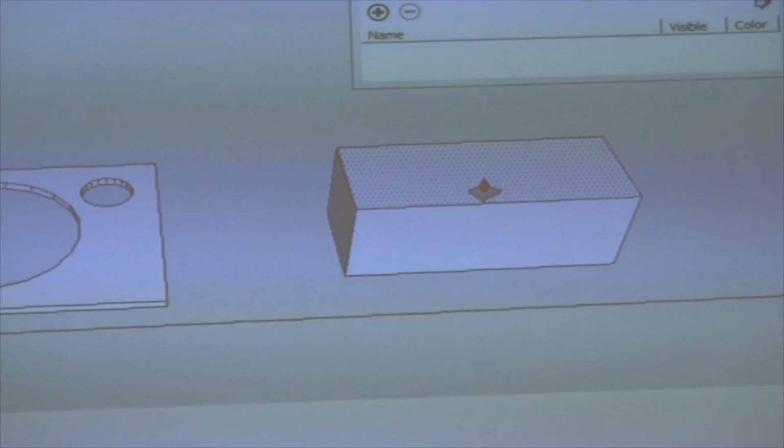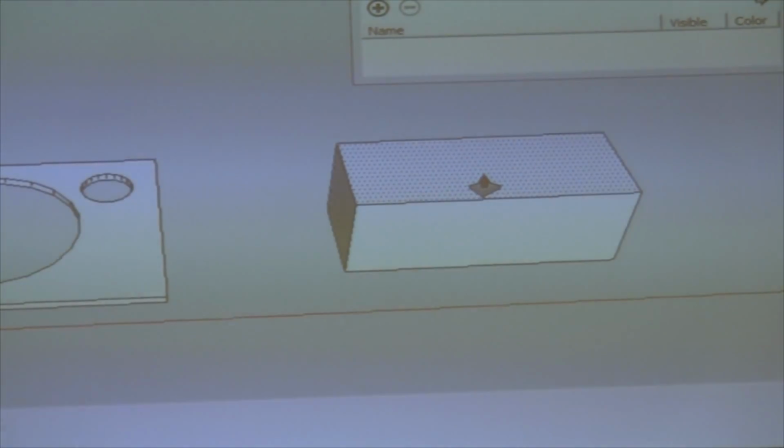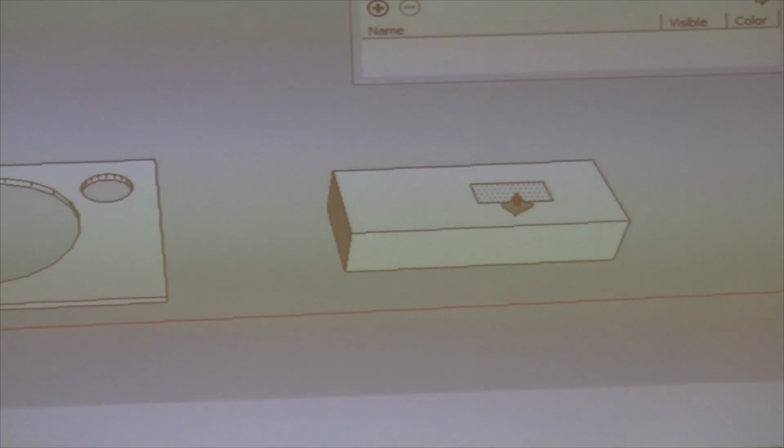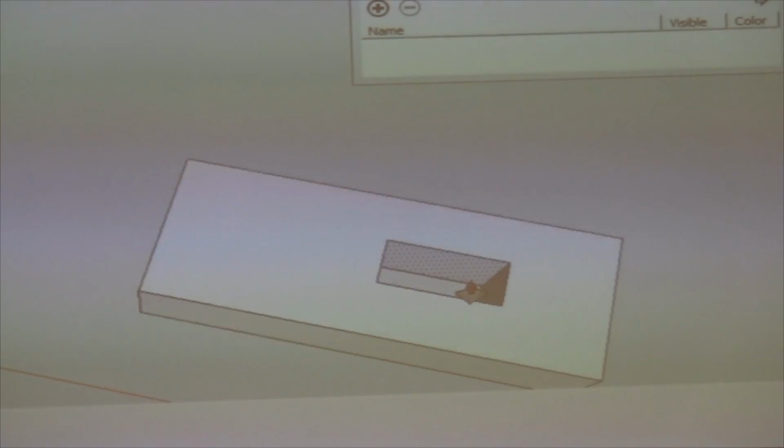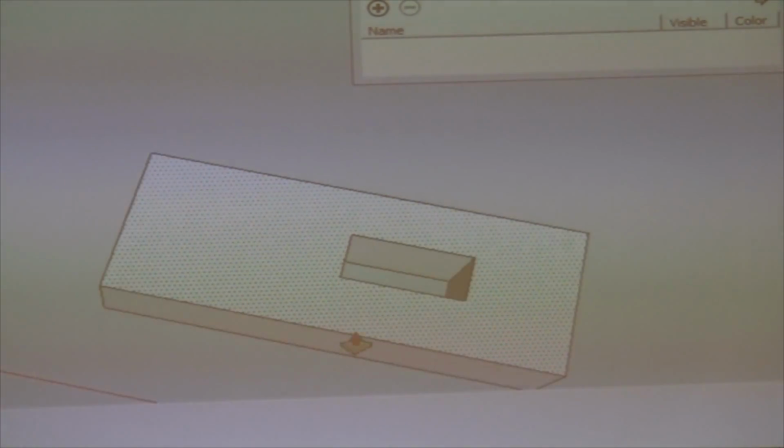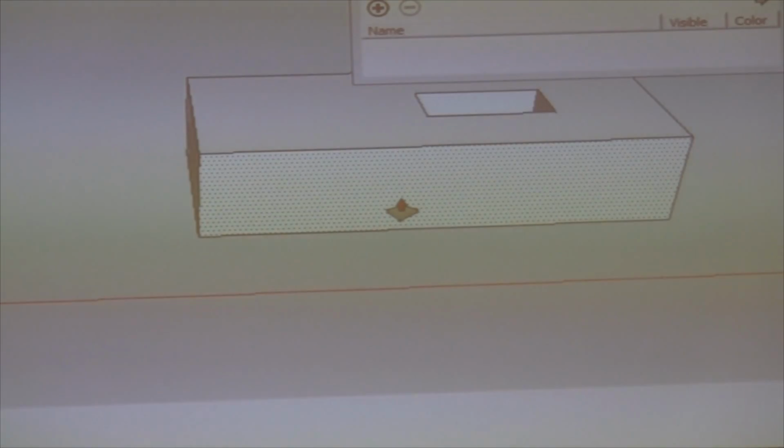I'm going to come up here and do a push pull in this direction, and that's important, which direction. I'm going to do that in this direction 5 inches. So if I make another rectangle and I select that surface and I double click, what's it going to do? Go up. Oh. Yeah, not what you expected. It went the other direction. So depending on the orientation of the surface, it may or may not give you what you want. So just be cognizant of that.